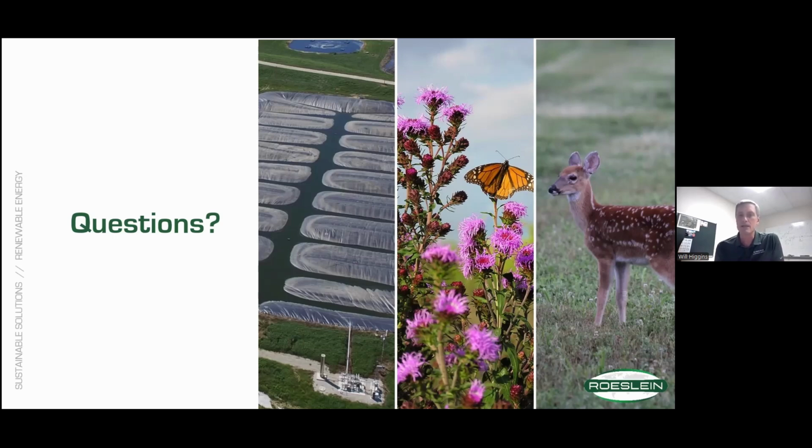And then as far as solids build-up over time, again, we're starting to see more of that in some of the older lagoons. Typically they're built with a lot of extra storage capacity because no one wants to remove the solids, even in an open lagoon very often. But the amount of solids is a function of the volume of the lagoon. We have lagoons that have been in service for 10 years that we have not had to go in and clean out. You can imagine that at the end of the sewer line entering the lagoon is where the settleable solids fall out, so you have this big pile that builds up over time.